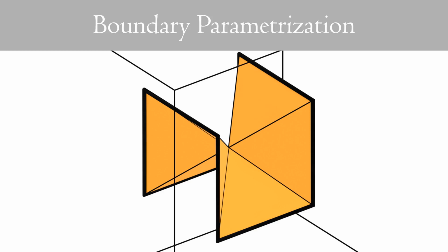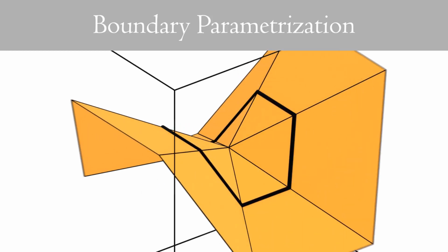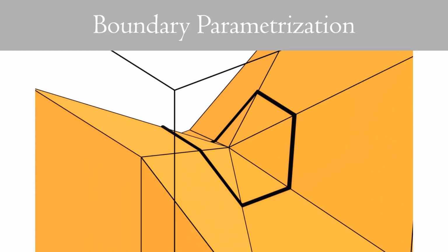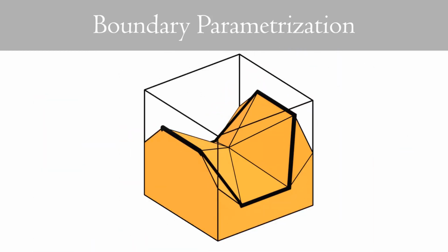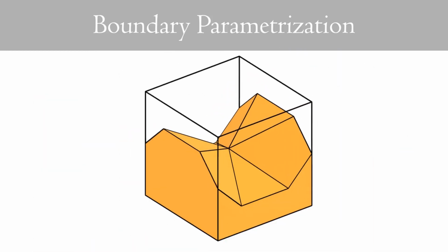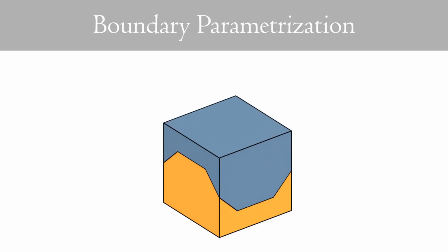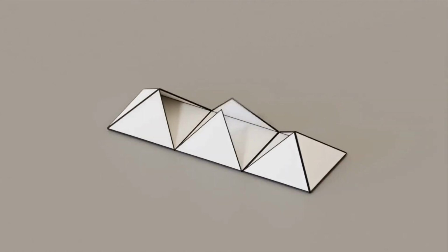From the constructed surface, we expand this surface so that it can bisect a fundamental cube domain. The resulting surface is extruded downward to be able to do a Boolean operation with the fundamental cube domain. Finally, a Boolean operation with the cube gives us our final shape. Now, we show the foldability of created shapes with different parameter and smoothing step choices.